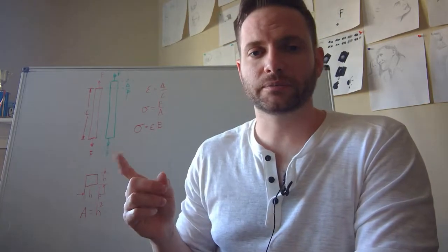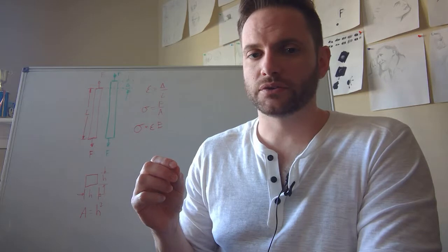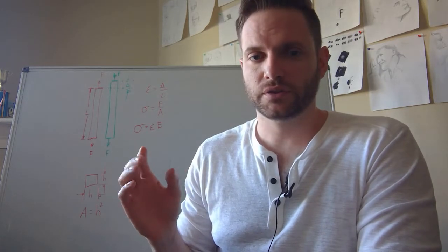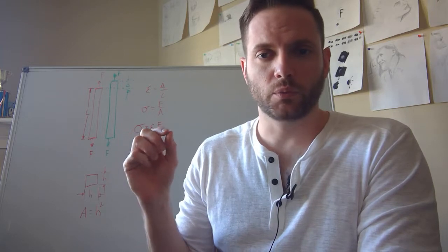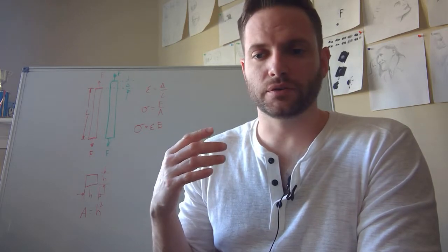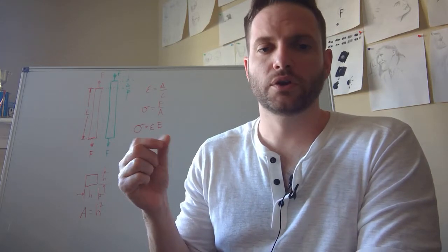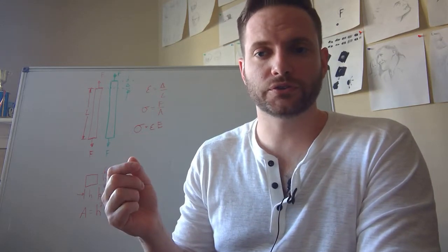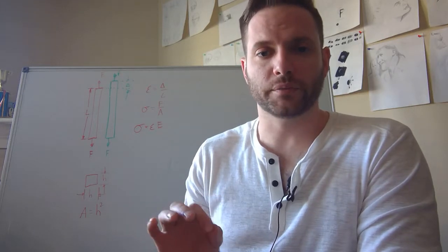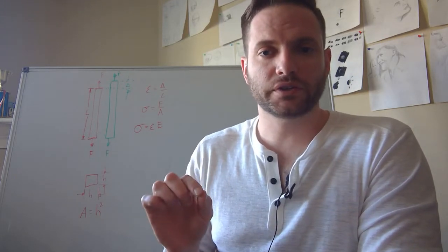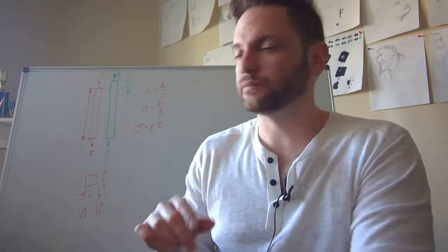Strain is the simpler of the two to understand, and all strain is the change in the length of something when it's growing, either due to being stressed with load on it, or due to a temperature change, due to a moisture change, or any other phenomenon. That change in length divided by its original length, that is strain.